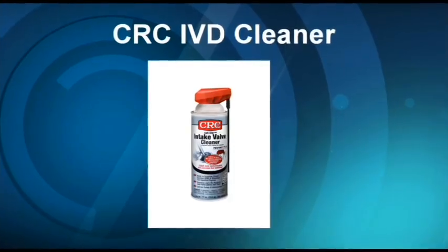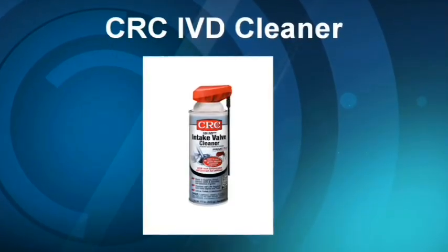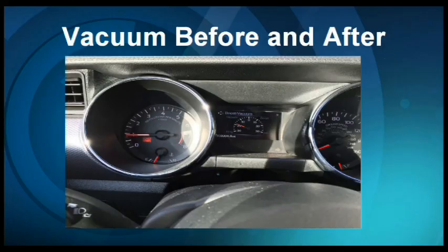Okay, we have completed the CRC IVD cleaning process on the Mustang EcoBoost. Now, I told you I was going to do a test. Let's look at those results. I've got a shot of engine vacuum and RPM before the cleaning. As you can see here, the boost vacuum gauge in the center of the dash is about 18 inches of vacuum, and the RPM is idling somewhere just under 1,000 RPM. So pay particularly close attention that the engine vacuum is 18 inches and just under 1,000 RPM. This is before the cleaning.